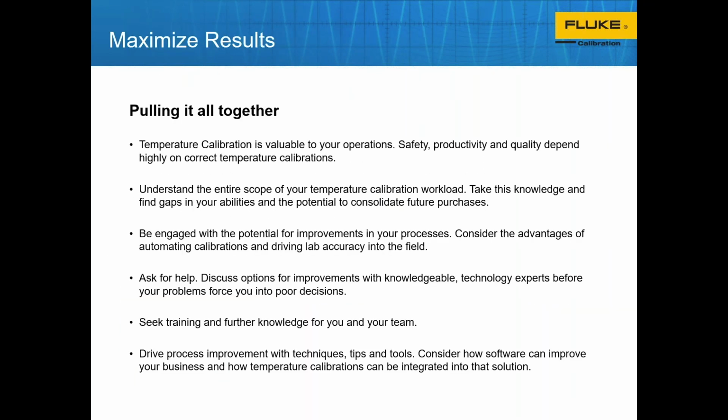Okay, pulling it all together, I notice we only have a few minutes left for questions, but hopefully the information is coming across clearly on your end. Just pulling it together, just understand that temperature calibrations are valuable. Understanding your accuracies and making sure you have the right equipment available to you to not only cover your day-to-day stuff, but those more specialized applications. It's never bad to take a specialized piece of gear to something that doesn't need the accuracy. You're just going to create more what they call guard banding or room to protect you from inaccuracies.